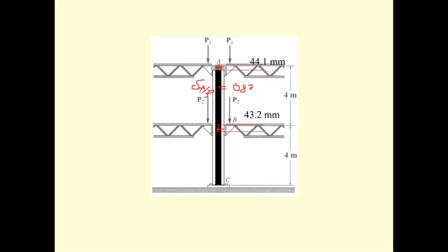And when everything is released, all the deformation of these two columns is going to be 36 millimeter due to the permanent deformation of the column BC. That's going to take this column down the same as before. Even though this one itself is still 4000 millimeter, this portion is going to be 4000 millimeter minus 36 millimeter.